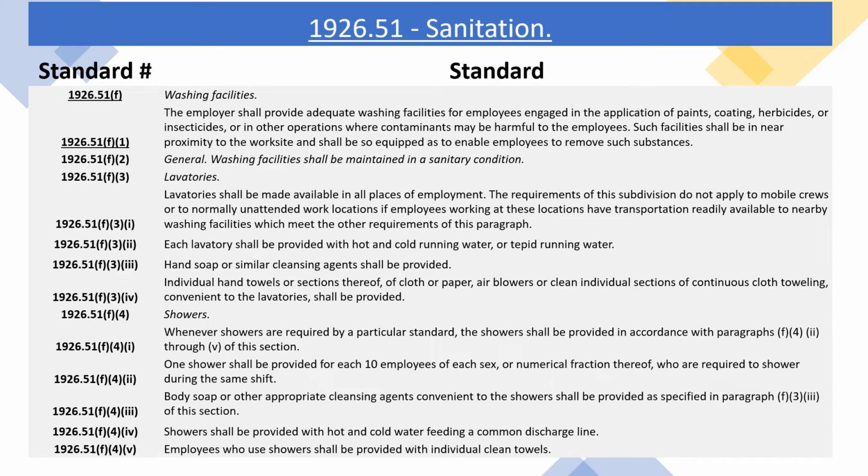1926.51(f)(4) Showers. 1926.51(f)(4)(i) Whenever showers are required by a particular standard, the shower shall be provided in accordance with paragraphs (f)(4)(ii) through (v) of this section. 1926.51(f)(4)(ii) One shower shall be provided for each 10 employees of each sex, or numerical fraction thereof, who are required to shower during the same shift.